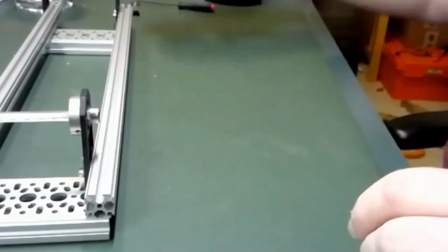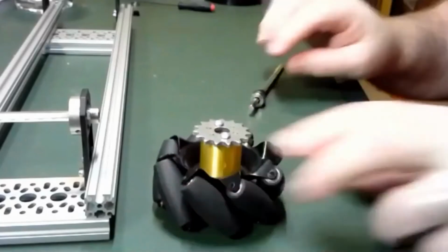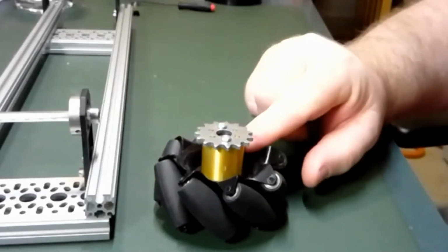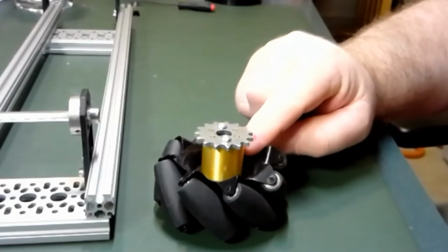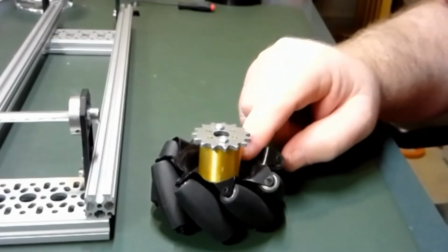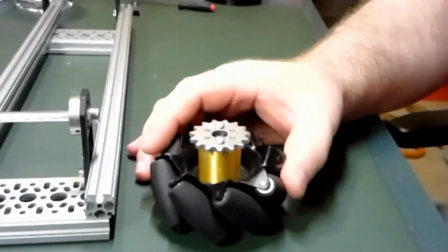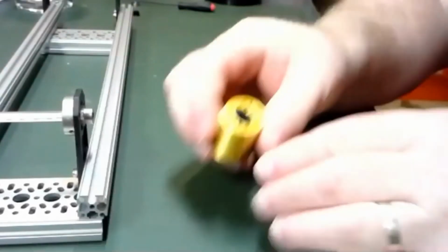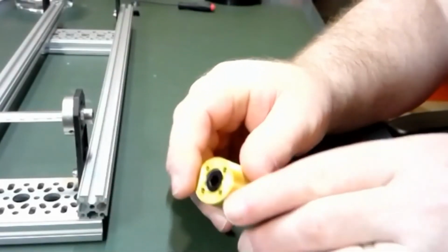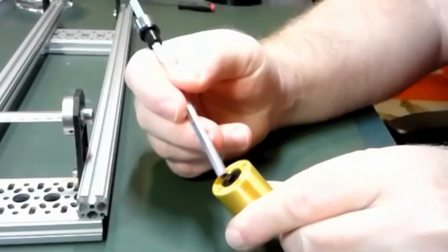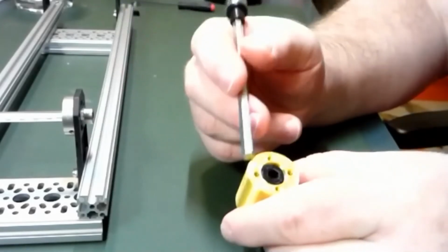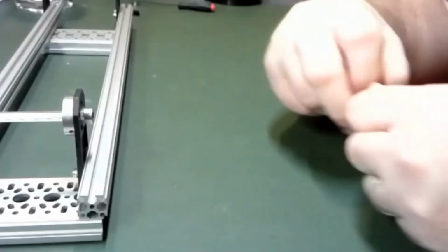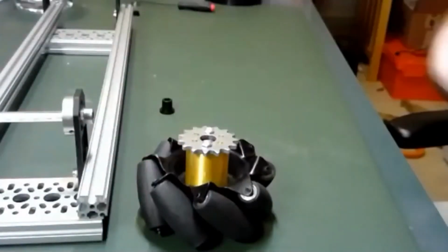The end result looks something like this. This is the REV Mecanum wheel with a 3D printed piece, and depending on how much time we have today, I'll be able to show the modeling of that piece in Onshape CAD in a little bit. The 3D printed piece has the bearings inside it. You can see the bearing right there, and it has the adapter to hold a hex shaft.